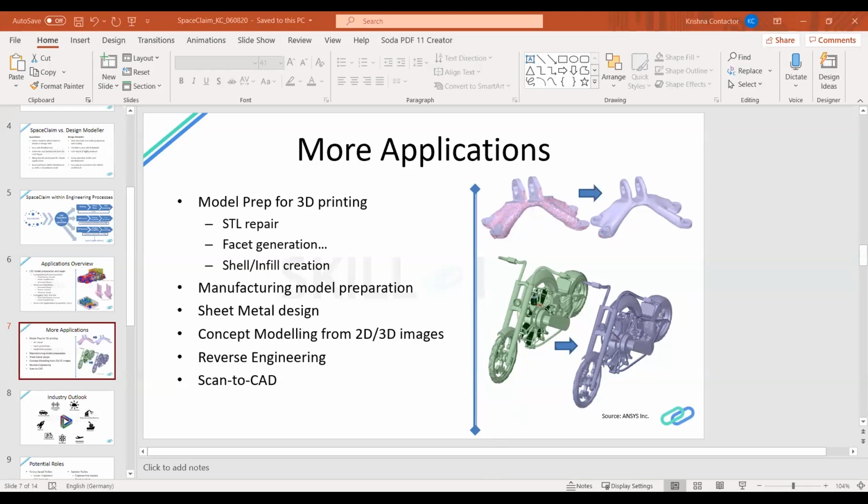Can we import geometry in SpaceClaim from other design software? Yes, you can definitely import geometry in SpaceClaim from most design software, from CATIA, SolidWorks, all the commercial ones, and also from different open source ones. You can import in different file formats directly as a solid part format, or as a STEP file, or an IGES file, or an SPI file. This can be exported from your design software and then imported into SpaceClaim. So this can definitely be done.